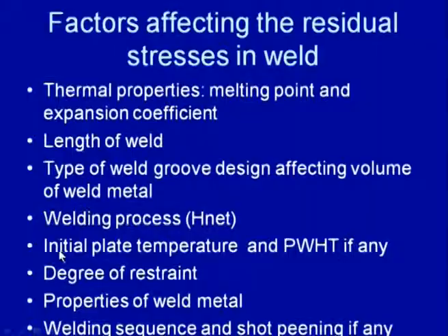So, the high energy density welding processes like the laser beam, electron beam and the plasma arc welding process, having the higher energy density, will be supplying very less amount of heat for developing the weld joint. Because of this, the reduced heat input to the base metal will result in a reduced magnitude of the residual stresses that will be developed after the welding. Then the initial plate temperature and post weld heat treatment.